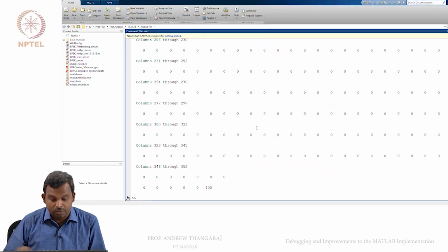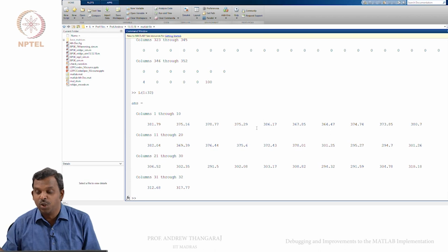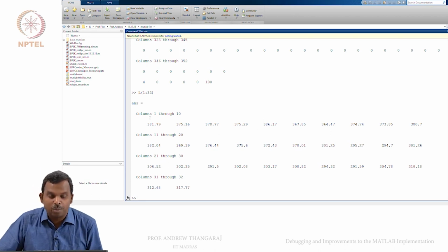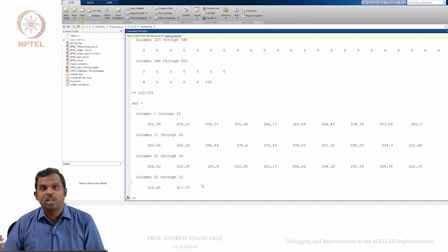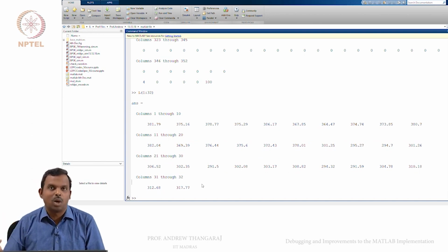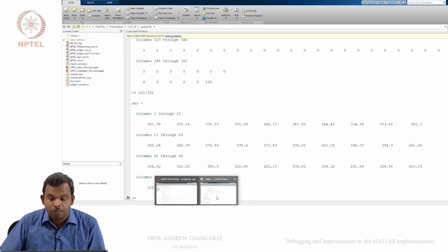It's also maybe instructive to see this L value. This is, remember, the total belief at the end of the iterations, 10 iterations, and you can see it's all huge, some 300 odd, and it's all positive. Okay. So, at the decoder, everything has worked, and it's also worked really, really well. And when you say it's 1, you're confident that the bit is 0, there's no doubt. The beliefs have really increased to a large value at the end of the iteration. So, maybe we should see this a little bit more.